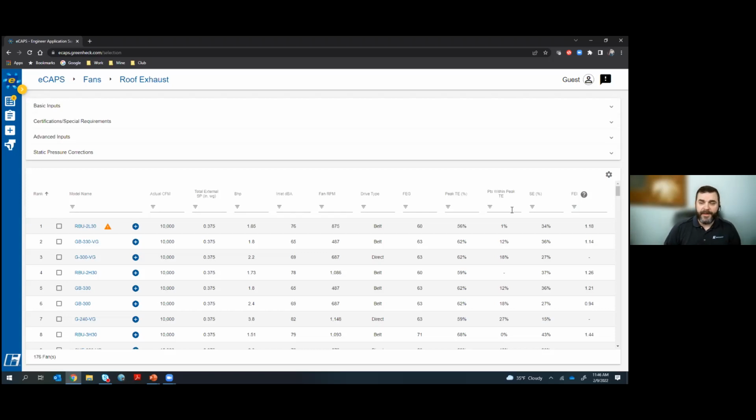Where if you look at an FEI, because we're just looking at power in versus power out, it is actually taking into account actual efficiencies and where you're operating at the curve. And then like we saw with those graphs of the FEI in the beginning part of the slideshow, a different operating point will affect where your FEI is calculated.